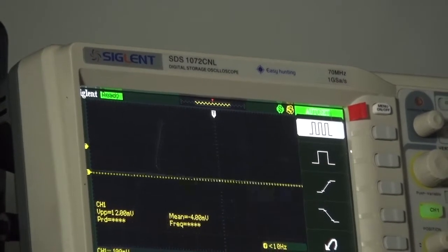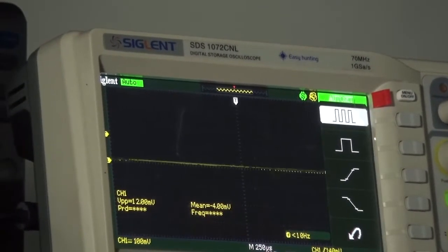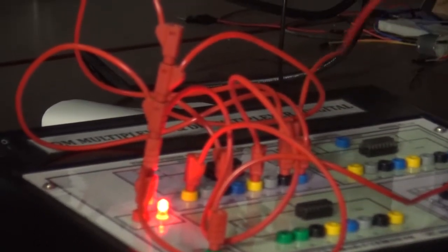So, you can see that we have sent several pieces of information through one channel, through this cable, no. So, this is one transmission channel. So, we have combined several users' information. Okay. Here we can combine 8 users' information into one channel using this time division multiplexer.